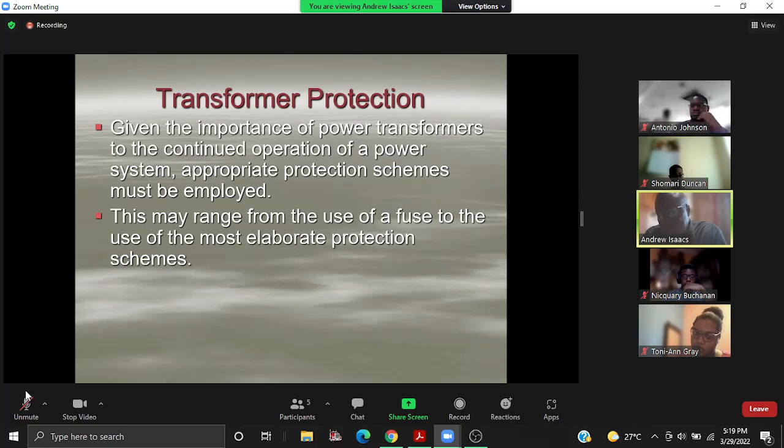However, when you're energizing or re-energizing a transformer, and this depends on the amount of flux retained in the transformer core, you're going to have current being drawn by the transformer to build the magnetic field within the core, but you're not simultaneously getting an output. Now, if we recall how the differential system works, that in and of itself should suggest that you have a fault. But we are just re-energizing the system. There's no fault. So we're going to talk about that.